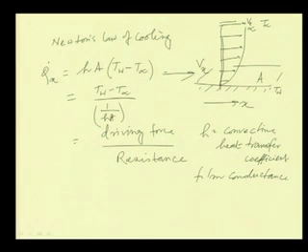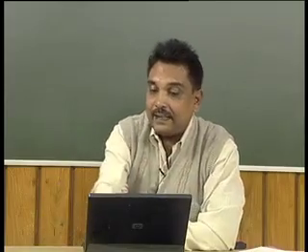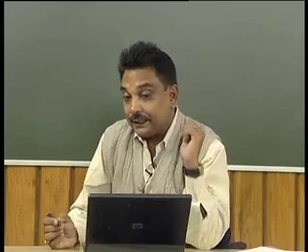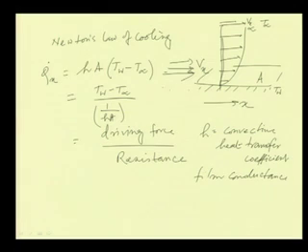What does it mean? On the wall there will be a film of the liquid, and we know that from the no slip condition, even if there is a flow of fluid over the plate, some of the fluid elements sticking to the surface, adhering to the surface of the plate, will not move, because the wall is not moving. So, those fluid elements also will not move, that is called no slip condition. So, some of the fluid elements will stick to the surface. They are making a kind of film,